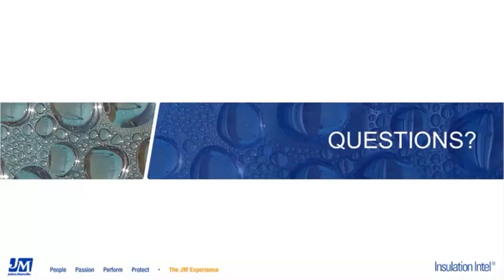I'm our technical specialist for the cold insulation area, particularly the closed cell insulations. As Meredith said, it really depends upon the insulation you're using. The first thing to remember is that the insulation's resistance to water should be viewed as the backup. The main resistance to water and water vapor is provided by the vapor retarder.